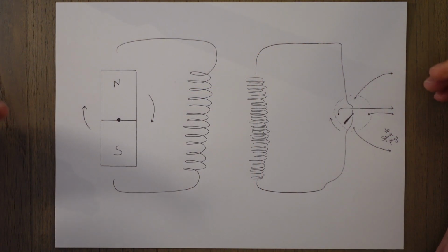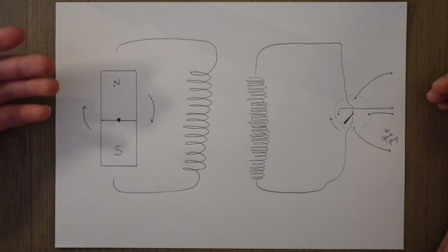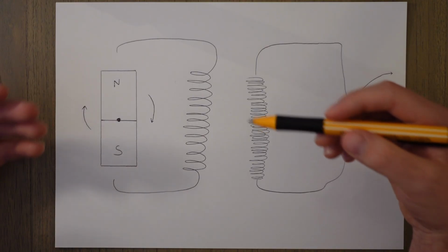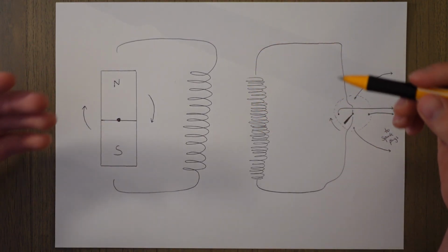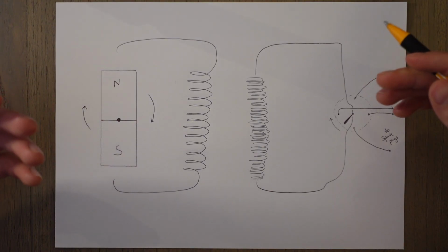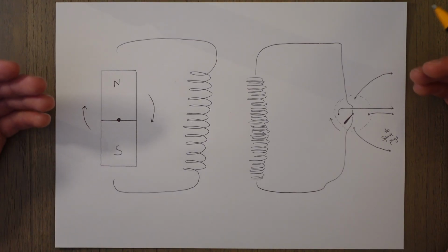So what we can do is attach some sort of spinny thing like the engine to this magnet to make it go round and start to generate electricity, which is what we want. So that's the first stage of the magneto system, generating a current. Another thing located in a magneto is called a transformer. This is a cool and quite clever electrical component that increases the voltage.